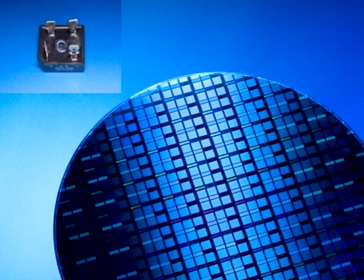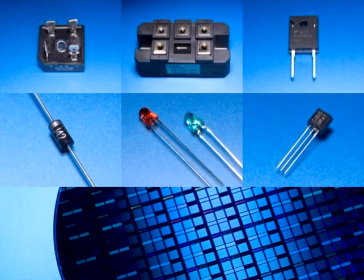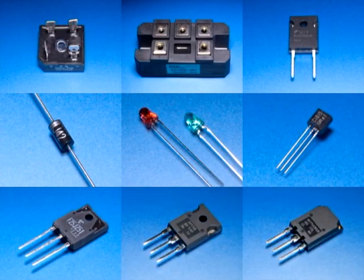When it comes to semiconductor products, including thyristors, it is important to guard against static electricity. Static electricity has a small amount of current, but the voltage can be several kilovolts or more. People are usually unaware that they have picked up electricity, making it possible for several kilovolts of static electricity to accumulate before they know it. Touching a semiconductor device in this state can cause the device to break down, a situation that can go unnoticed, since visibly it does not appear to have changed.